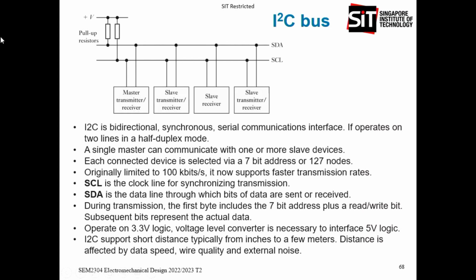That's why when nobody is using the bus, the output will be a 1. Only when you need to put information, then the output becomes a 0. So if the bus is left unconnected, it will not create havoc because the output is always a 1, or floating.